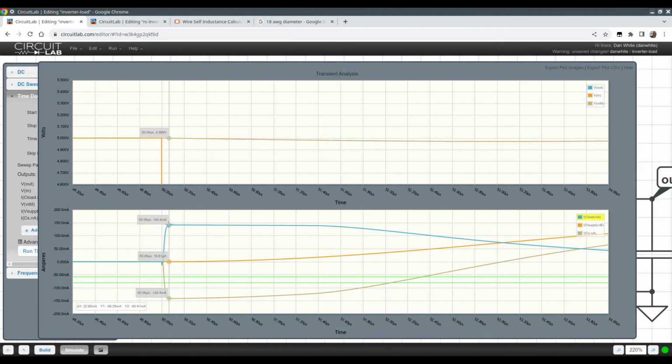Here's the load capacitance. Our signs are flipped, but you notice that all of the current charging my output load, which is the blue line, is coming from the CS capacitor, instead of having to flow through the wiring inductance. Which is exactly why we don't get a large di dt or a voltage across our wiring inductance right at this moment, right?